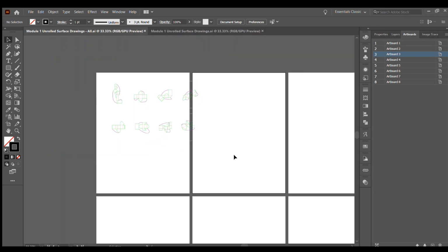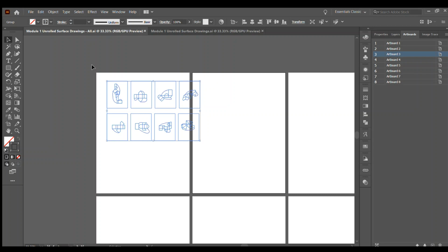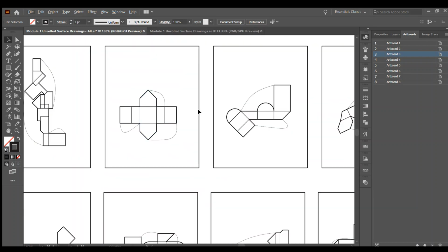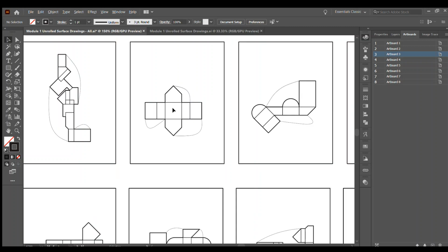is that you want to make sure all your lines are 100% black. So in order to do that, you want to go to the color, and then click black here, and then you can also click here, make sure it's CMYK, and then go to 100% black, turn all these off, so that way it's just 100% black. And you can already see here the difference in your drawings, and these look like architectural drawings now.